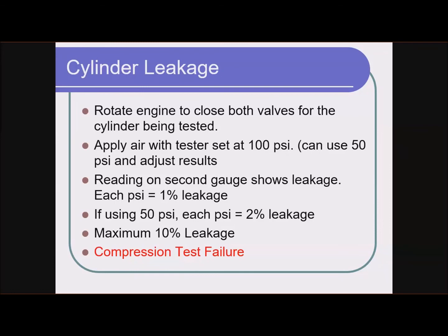And like every other spec, if it was 11, would I say that's definitely the problem with the engine? Well, maybe not. That Snap-on gauge allowed us 40, but I've done this test on a lot of good engines, just demoing it, and it's always less than 10 on engines that are running well. So take that for what it's worth.